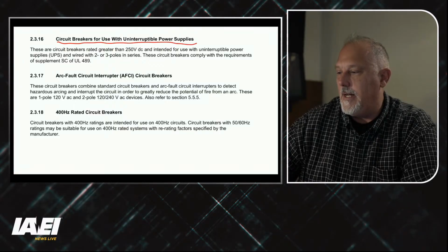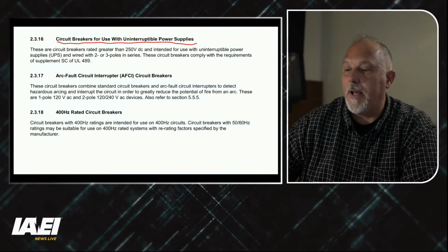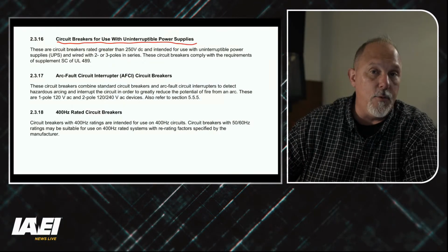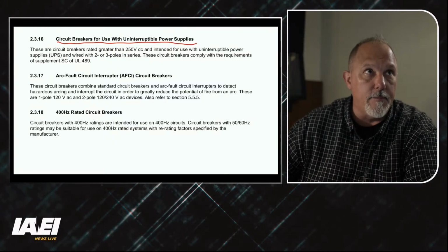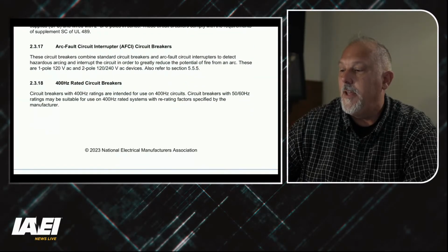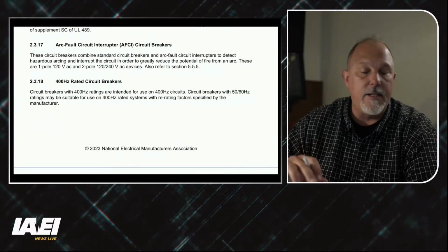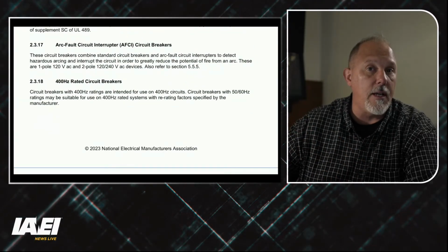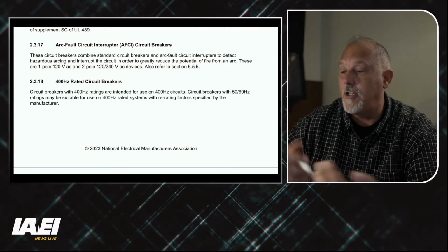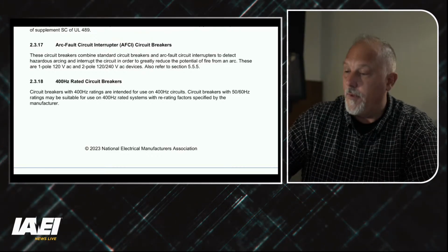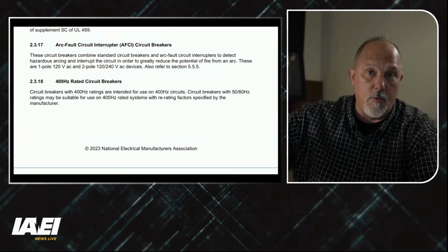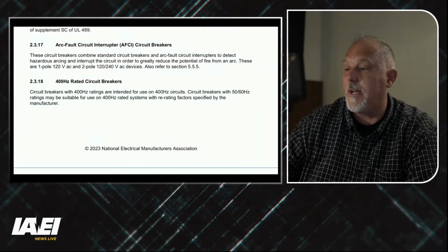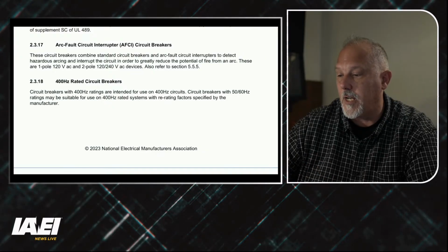So in any case, circuit breakers comply with the requirements of Supplement SC of UL 489 for uninterruptible power supplies. There's the AFCI circuit breakers that detect the arcing and sparking. That doesn't do shock protection, doesn't do the 489 nature of the device, which is the thermomagnetic, etc. But the AFCI just does arc protection.